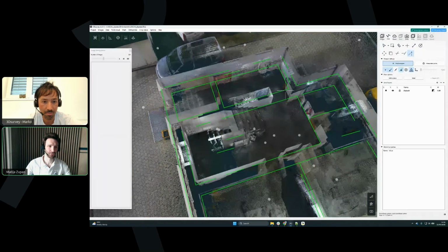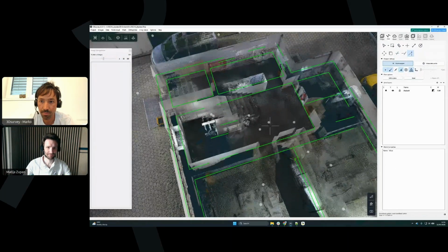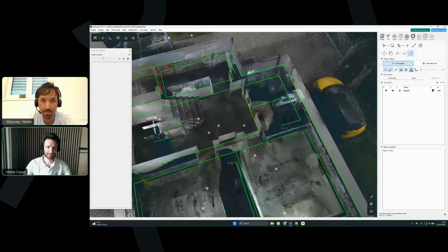And we have these rooms pretty well done, but what is this? Here you will use the trim tool. So I want to trim this little piece out because this is the wall and that's better. Okay, let's go back to intersect. Yeah, a bit more intersecting. This one with this one. And let's say this one with this one.